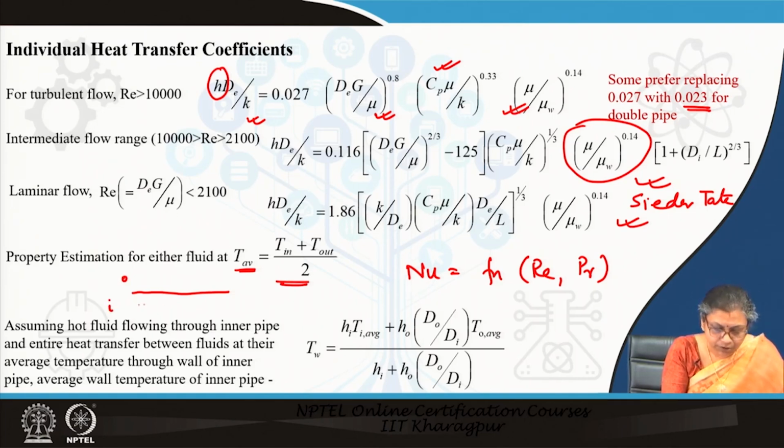So, for this particular fluid what is Q equal to? It is HI AI, and heat transfer is occurring say in this direction. Say for example, the inner fluid is the hot fluid. We just assume; it does not matter even if you assume the outer fluid to be the hotter fluid, the derivation in no way is going to change.